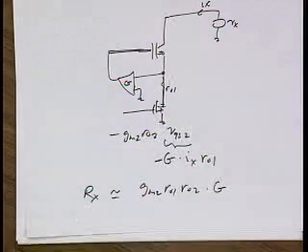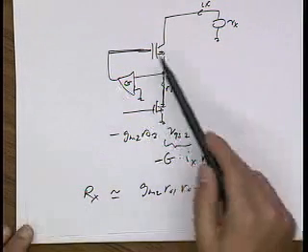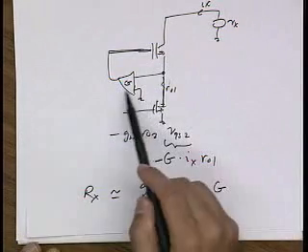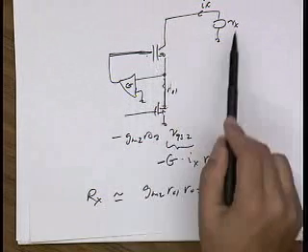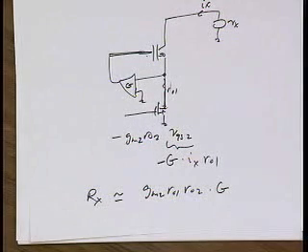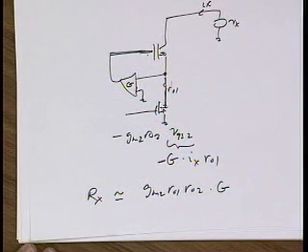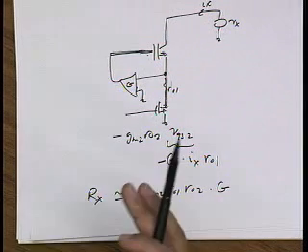I think I see you saying it. Noise, right? Yeah, noise, right? Potentially this thing can have higher noise because this amplifier obviously is noisy. It injects noise onto the gate of this device, which makes its way to the output. Without doing any math, are you concerned about that noise at low frequencies? Debo, you're shaking your head. Why not?